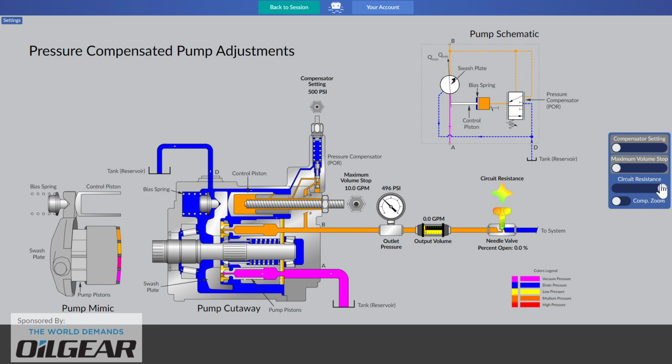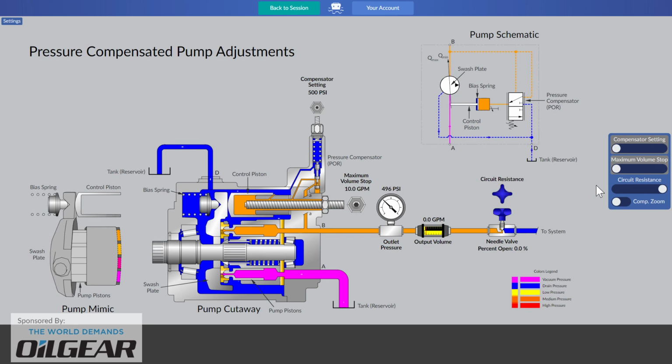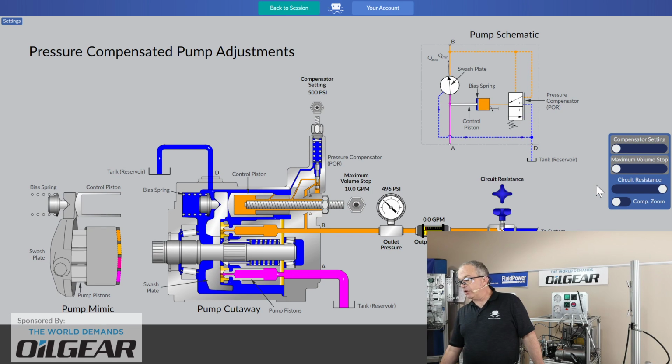For many of you, that will just be returning your directional valves into the neutral state and making sure that they stay there if they are blocked P-port directional valves, as they commonly are with the use of a pressure compensated pump. So there we are. Our system is blinded, and our pump's flow has been blinded out.